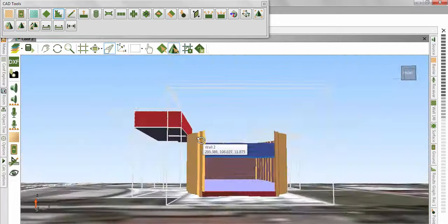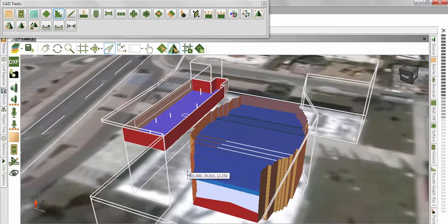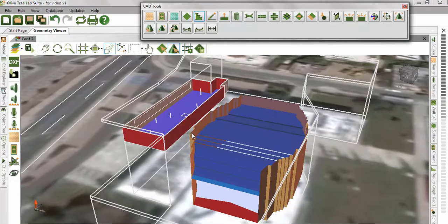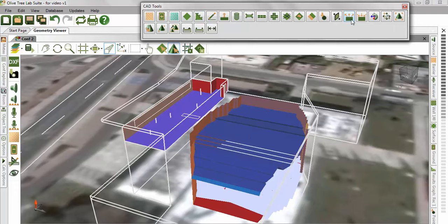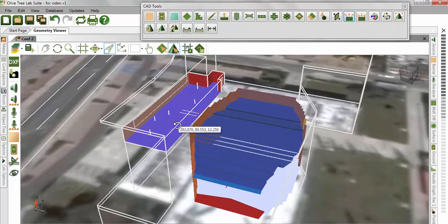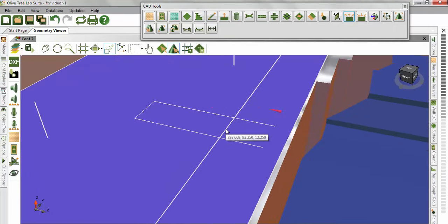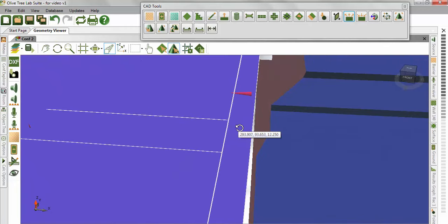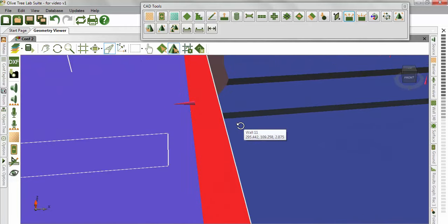Before we proceed, we need to check the normals of the library. The normals are the reflected sides of the surface and only apply in room acoustics and open plan office, and they're not necessary for outdoor sound propagation. The theatre's normals are already corrected, so using the Show Hide Normals tool, or N for shortcut, will display the normals of the room. The normals should be pointing inwards and are highlighted by a red cone. The non-reflected sides appear as transparent when you're facing the wall directly.